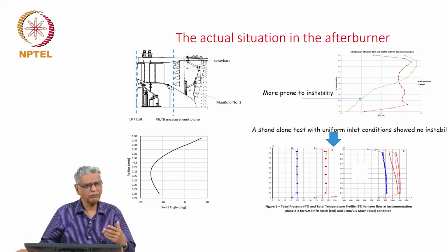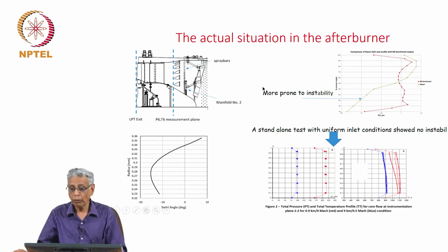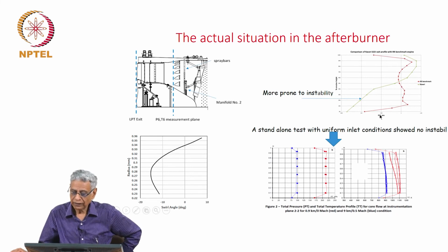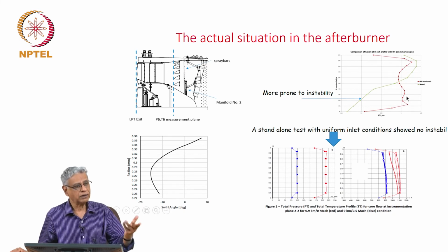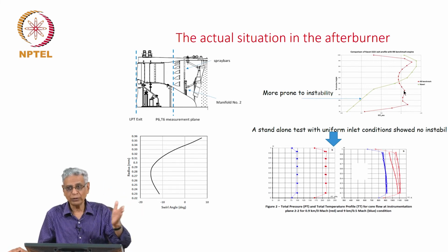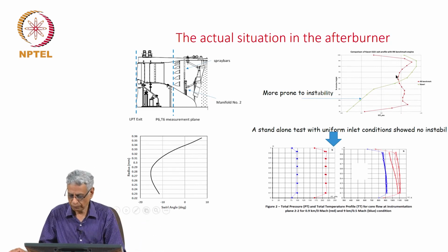So, this was done without necessarily appreciating this particular effect, and what more, you will see that the pressure profile for the current situation is like this, whereas the expected pressure profile from a benchmark design from Rolls-Royce is like this. The pressure must be uniform, flow rate must be uniform, is what the expectation is. Okay? But if you violate that, to some extent it will work, but if you violate it much more, it will kick back and give you instability. That is the inference. Okay?